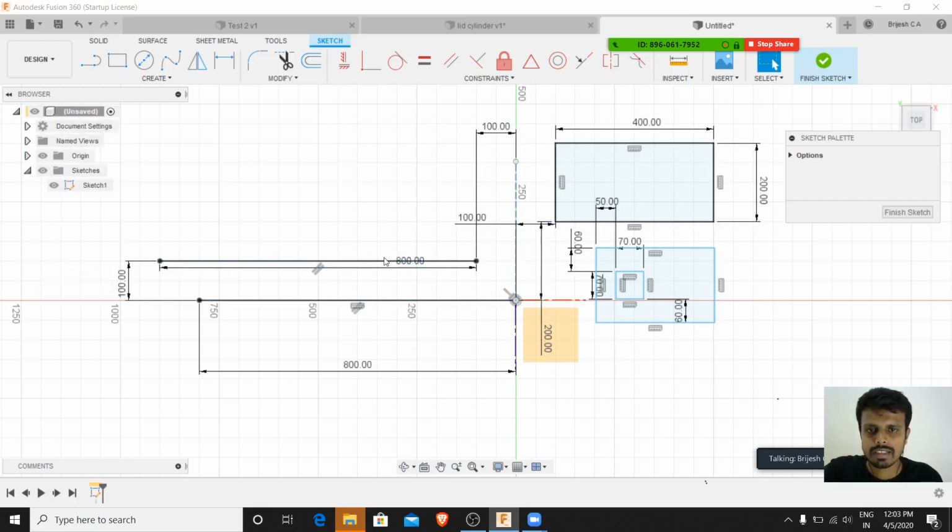Yeah, this is a construction line, this is the line. Now we use constraints for making these parallel to each other, also the same dimension, and also the distance between these lines. So this is how you define constraints, and when you define constraints, your sketches or drawings are more foolproof. You always have a constrained object, because when you are doing bigger sketches, if you do not have all the constraints in place, when you try moving something, something else will move and you will not have the object that you are expecting.